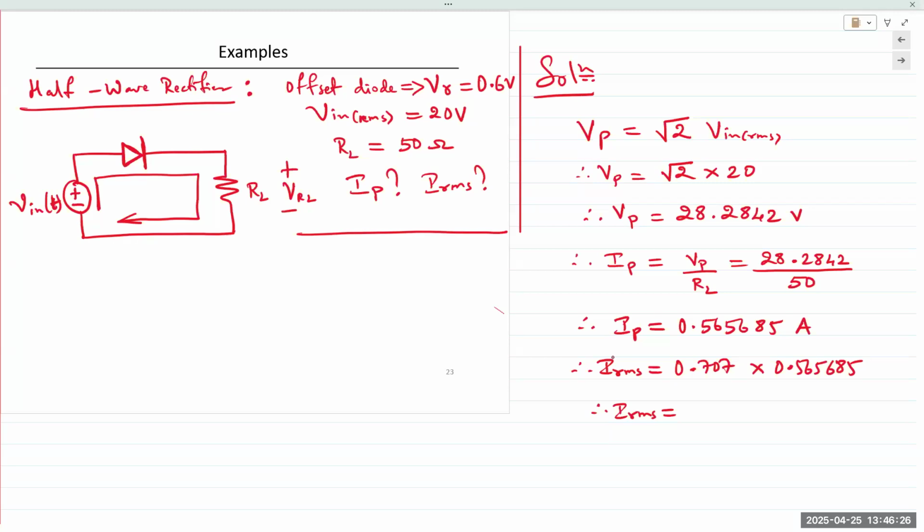That's the top. So this is without the diode voltage drop. So if you're applying 28.28 volts in there, your output peak value will also be 28.28 volts. But then the RMS value for that voltage will still be the peak divided by √2. RMS times √2 is the peak, it's always in the positive way. Negative, so that's where the DC comes from. That's why we have two different notations.